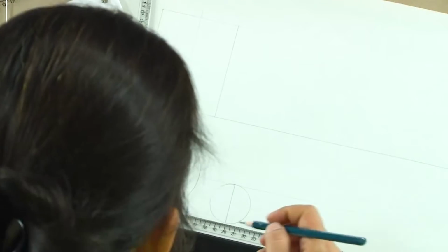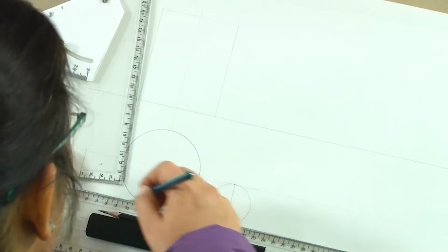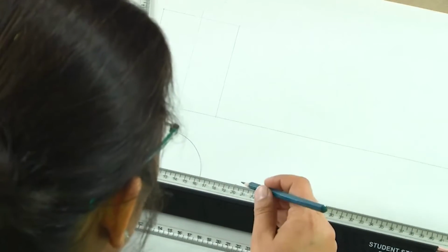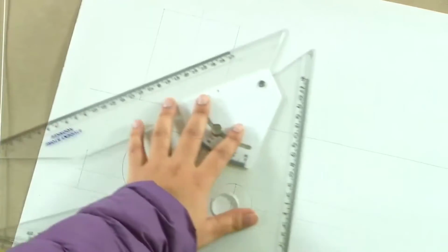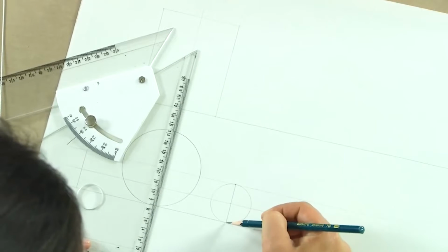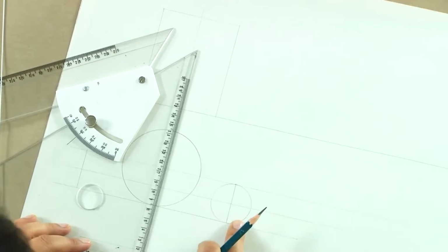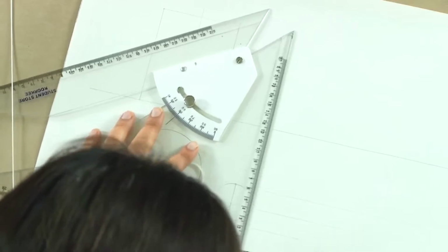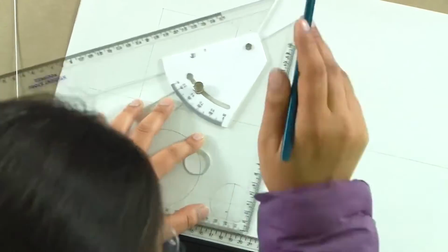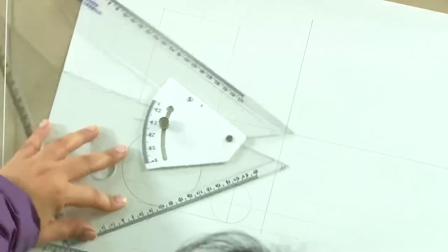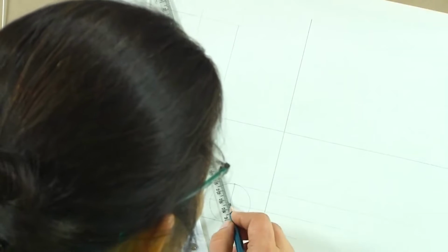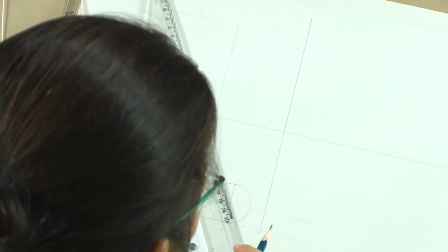So, this is our reference circle which we are going to take for drawing the projections. To start with, actually the cylinder is right up till here. I am just drawing the circle for the reference. So, what we can start with is by looking at the side view. For this, let us first divide the circle into 12 equal parts.